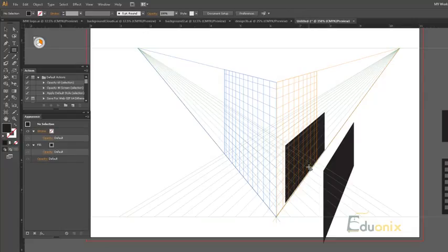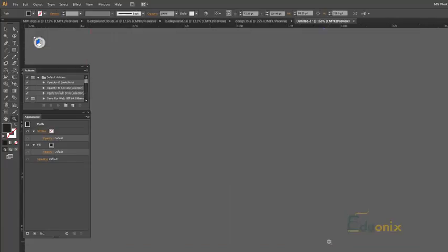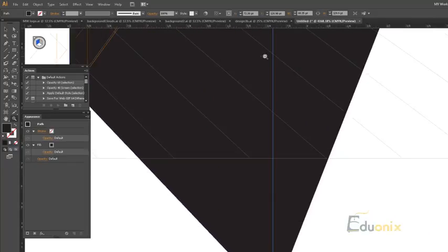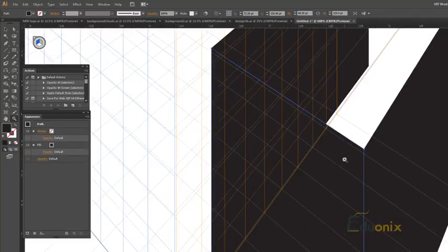And I currently have the rectangle tool highlighted, so I want to find an anchor point and just start drawing it out. As you can see, it's in the wrong angle, so I just hit 1, because I'm doing this face between these two sides, the one closest to you. And you just want to make sure you find anchor so that it snaps in. Since you're drawing it in perspective, it should be totally snapped into these points, as you can see.